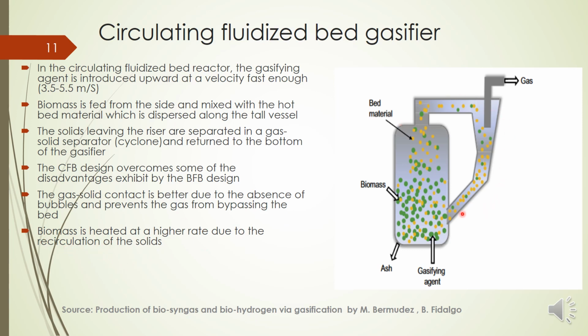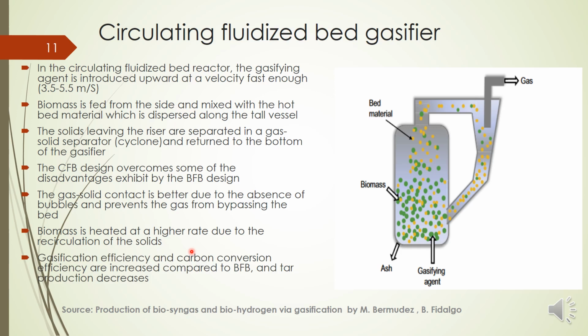Here we are recirculating the hot bed material back, so that will increase the overall heat transfer rate of the gasifier. Hence we have increased gasification and carbon conversion efficiency, and tar production is also less.